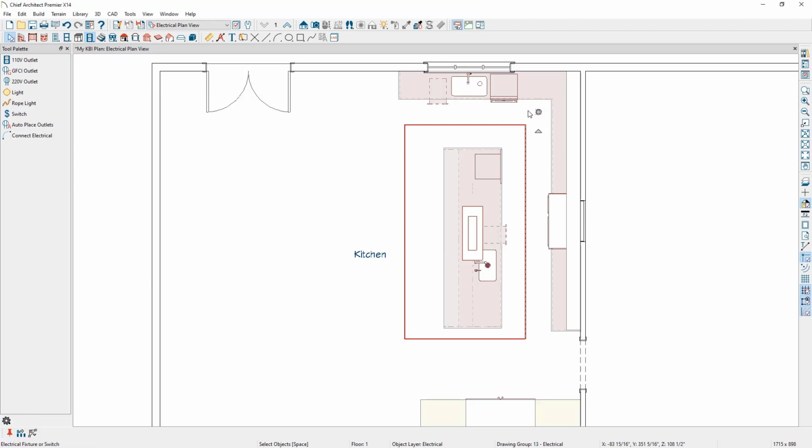and you can see how my mouse changes there when I come over to the can light. And using the right click on my mouse, I'm going to click and hold that right click, and you can see that as I move it down the plan, we add lights, and then I'm going to release my right mouse button, and then while moving my mouse to the left while not clicking anything, we'll place additional copies every 78 inches. When you're happy with how they look, you can left click, and they'll be added to the plan.